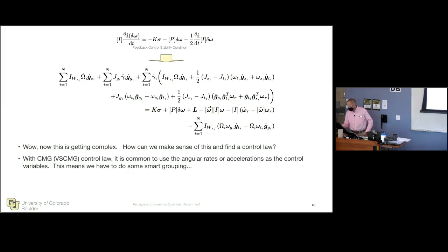This is what we had before with the reaction wheels. There was also some compensation for the reaction wheel gyroscopics. So just like with reaction wheels, we had that in our LR part 2. So as the wheel is spinning, and if I'm holding a constant gimbal rate, as the spacecraft tumbles, you will have some gyroscopics. But there's nothing I can do about that, because I can't control the gyroscopics because it's dictated by the spacecraft tumble. It's not something I can prescribe.